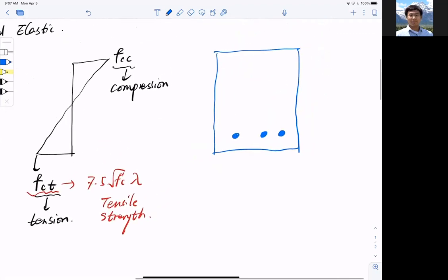So first of all, I'm going to remove these reinforcement. When I remove them, I'm left with 3 holes, and these are empty now. Put the bars out basically. And then I fill them back in with concrete, right? In addition, I also add another 2 little wings on the side. I add the 2 little wings on the side, okay? Because I fill it up with concrete now.